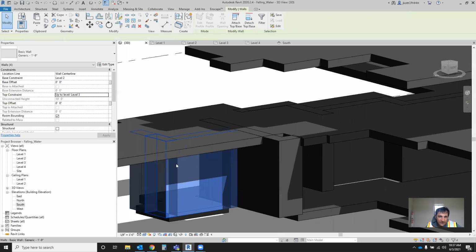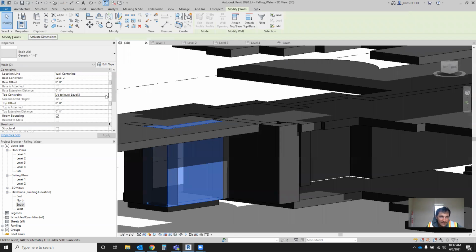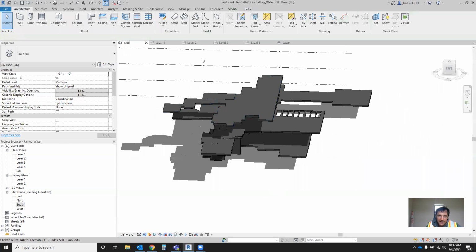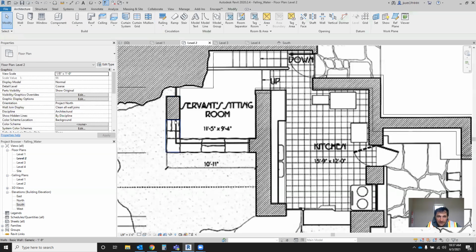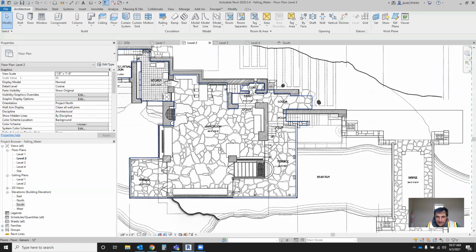But these levels are only half height, so as to create a balcony. So rather than be -4, we're just going to make them 4 feet tall. And now you can see how that balcony works. So in areas like this, where you have no poche, this is a poche right here. You can see the block. Those are half walls. Similarly to this wall here, it's a half wall handrail.